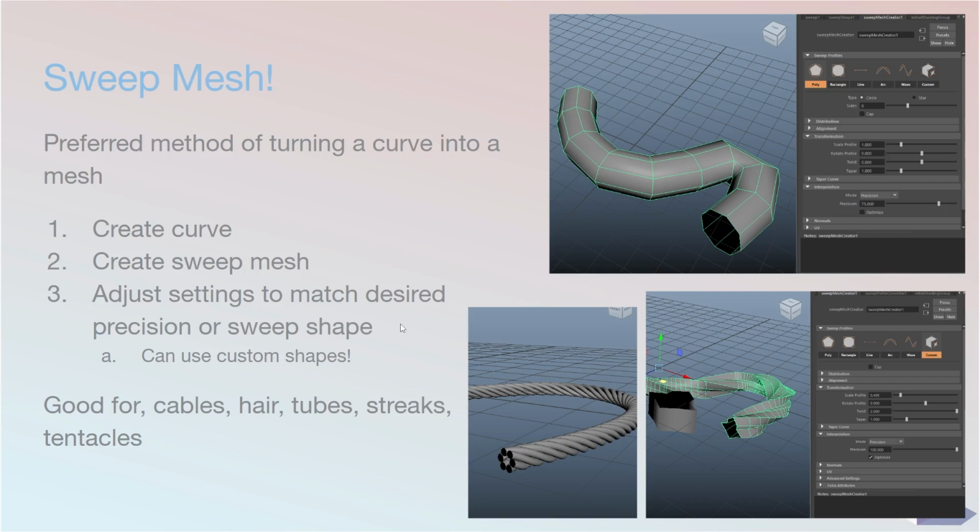I love the sweep mesh. Essentially, you click a curve, you click the sweep mesh button, and bam, it generates a mesh that sweeps across the entire curve. And then there's a bunch of settings here, like the precision.